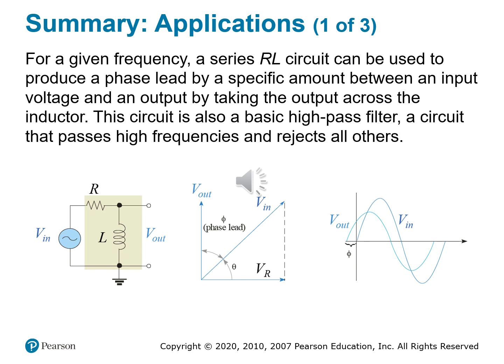Now for the filtering. This circuit behaves as a basic high-pass filter. At low frequencies, the inductor resists current change, so very little voltage appears across it. At high frequencies, the inductor passes change easily, so most of the voltage appears across L, and that becomes your output. So low frequencies are blocked, basically, and high frequencies pass through.